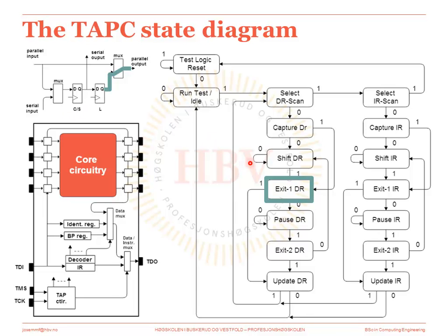When this happens, we have shifted into the boundary scan register the required test pattern, but we have not yet updated the outputs. That is to say, each capture shift stage will now hold the new value, but it has not yet been transferred to the latch stage.